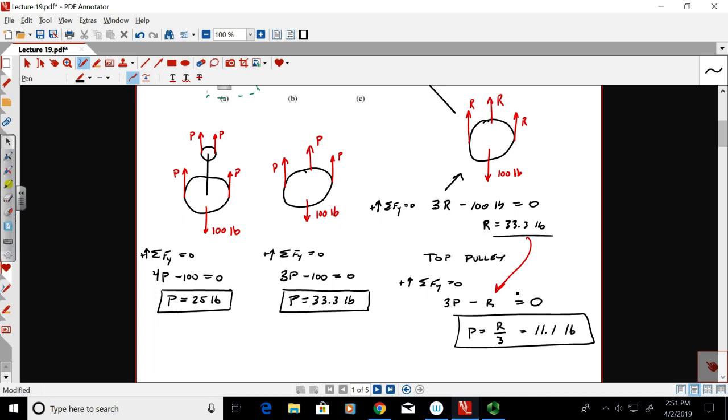It's just like gearing, if you've ever worked with any gearing systems, and you'll learn about this in machine design. You can only get gearboxes to do so much of a magnification. Your cars have gearboxes, but what's the highest gear ratio in most cars? Like 6-to-1? I don't know. Not that crazy, right? It's maybe a little bit more than that. But having a gear ratio like 100-to-1 is really hard to do. Your gears have to be super precisely done, and that's hard to do.